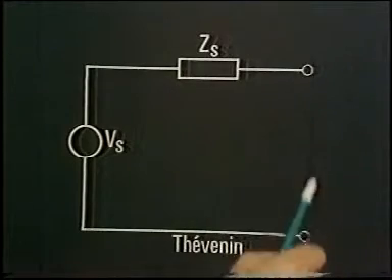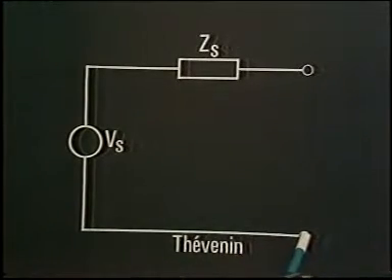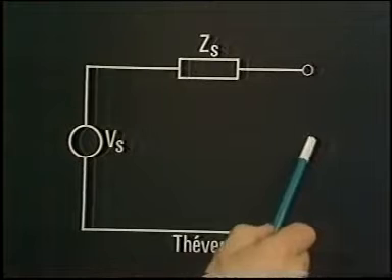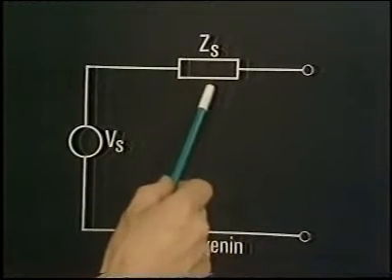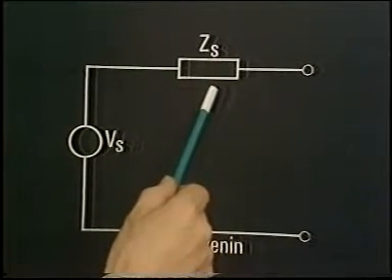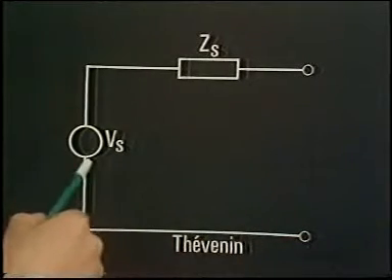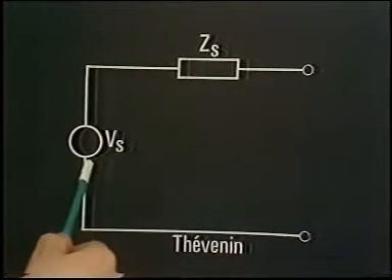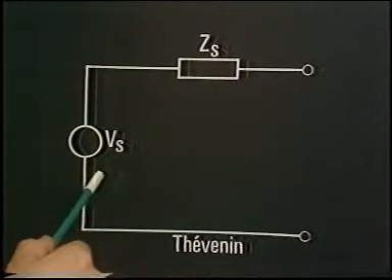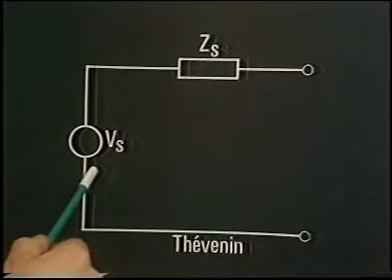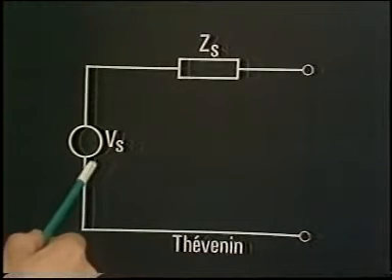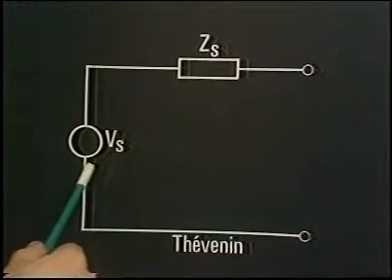Now, what we've actually been measuring is the voltage at the output terminals of the device. I've been using an oscilloscope to do this. It has a much higher impedance than the output impedance of the transducer. So the voltage I'm measuring at the terminals is virtually the open circuit voltage, which is the same as VS, the source voltage. We've measured that at a particular frequency, but we know from earlier parts of the course, Unit 8 and Unit 9 told us that that voltage also varies with frequency. So we'll need to take that into account as well in characterizing the circuit, the transducer.